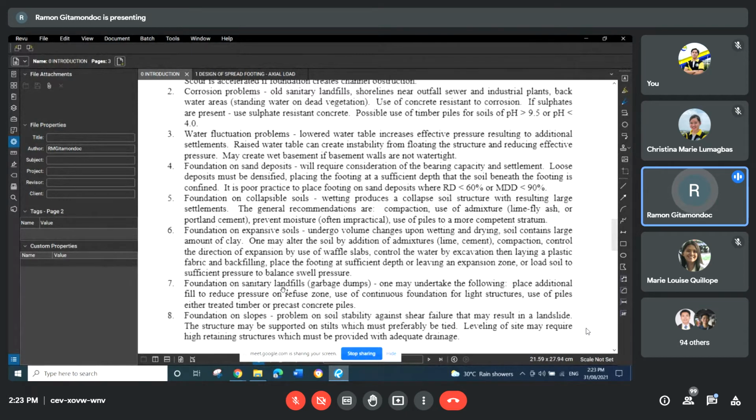And if your foundation is placed on top of the soil, then there will be upward and downward movement of the foundation. And if this is not controlled, then that will result into additional stresses in the superstructure of the building. So one way to deal with expansive soil is to put a lot of weight, that is to counteract the expansion. But usually this is an expensive solution.